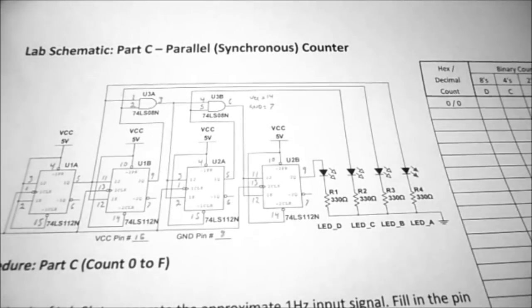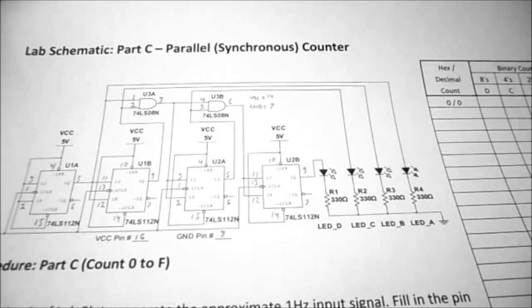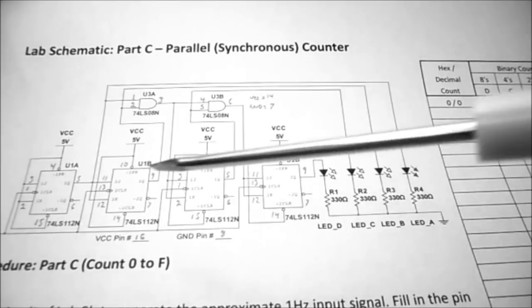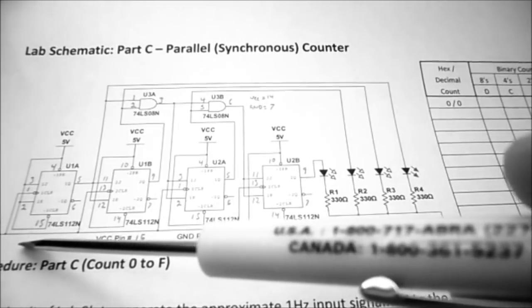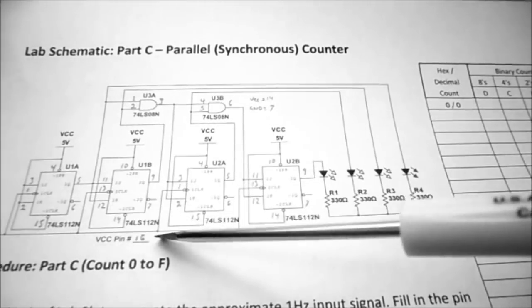So part A and part B were ripple counters. Now we're going to build a parallel or synchronous counter, and you'll notice the clock signal comes in and the clock goes to every single one of the flip-flops.